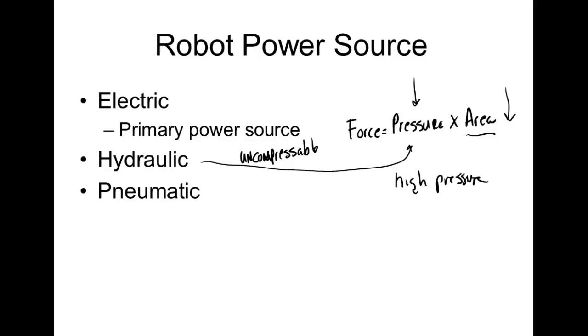So pneumatic cylinders, if you don't do something with the flow control, it's hard to control speed. You can get a rough idea of a speed control with a pneumatic system. Pneumatics can be jerky if you don't do anything with them. And with pneumatics, they'll talk about meter in and meter out. So what we have to do is meter out, which works out okay.